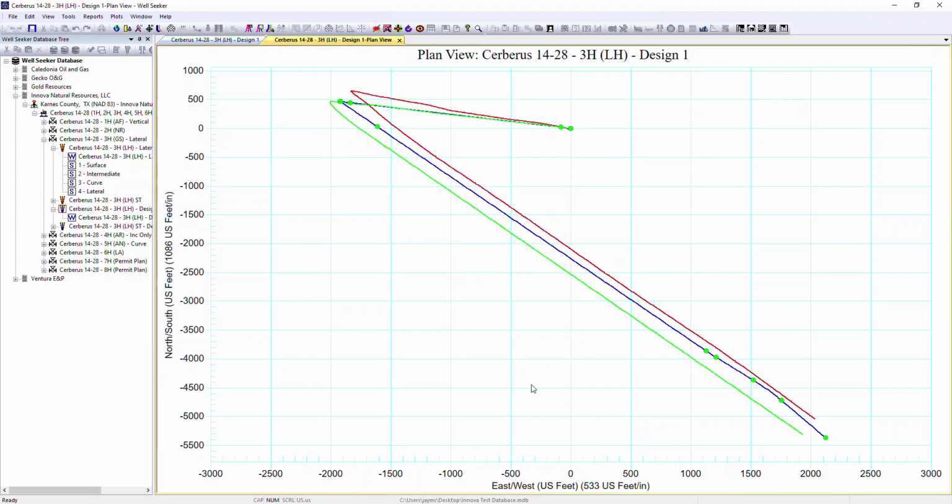One thing that should be noted is in any of the main user interface charts, it is possible to skew the aspect ratio, and by that I mean have a different scale on the X and on the Y axis. In the wall plot composer, this is not something that you can do. You have to maintain the aspect ratio within the wall plot composer, and as a result you will not be able to achieve something like this where we have got two different scales for the X and the Y.